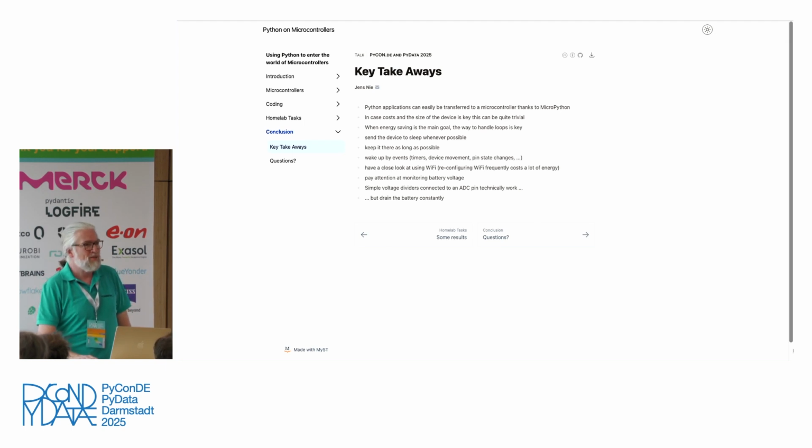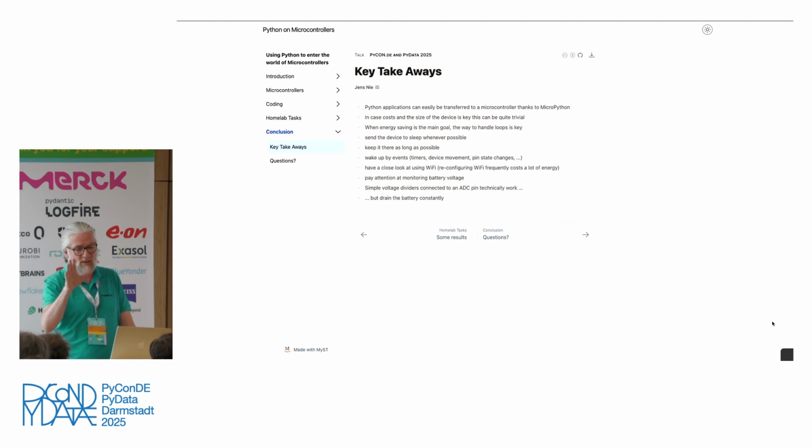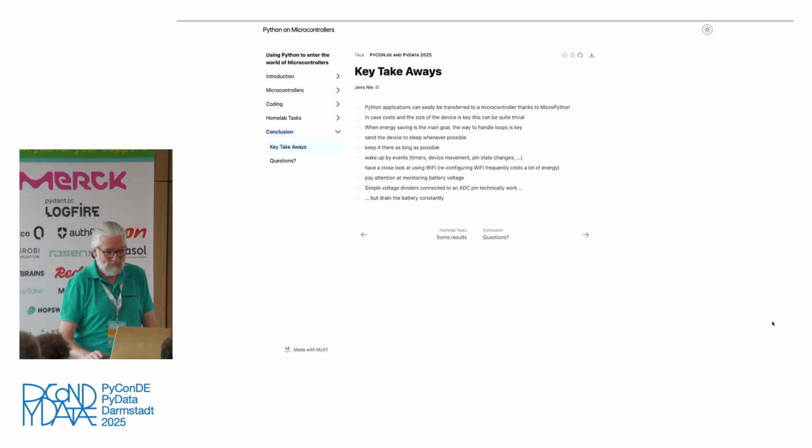Some have bad ideas for this, sadly, by just using a set of resistors in series, and in the middle pin you can really grab the voltage level then and monitor this with the ADC that you have on the microcontroller. But this series of resistors drains the battery. That's a really sad story, really, because the idea was right, and it was just one transistor missing to get it really correctly. But here we are.